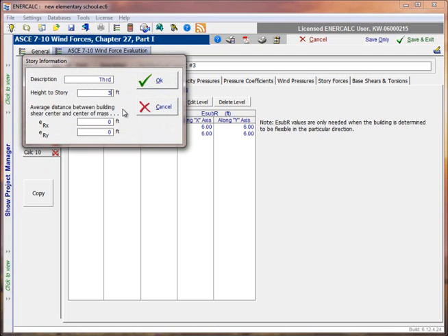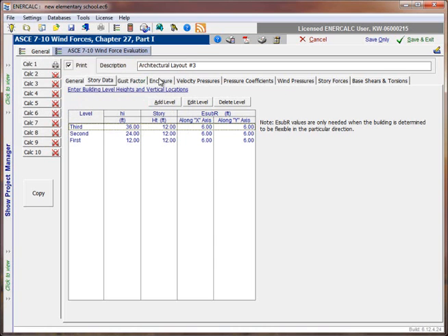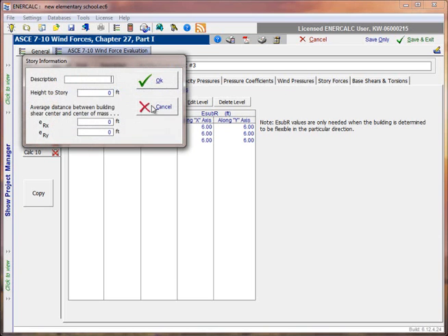I'll assume that the height to that floor is 36 feet, so again a 12-foot floor to floor. And then finally I'll add a roof on the building. And I'll assume here that our mechanicals distribute underneath the roof, so we've got a higher floor to floor of 14 feet, bringing the height to story to a total of 50.